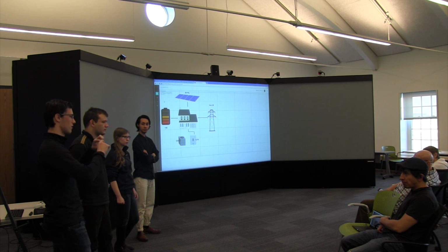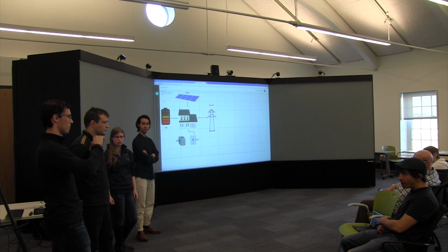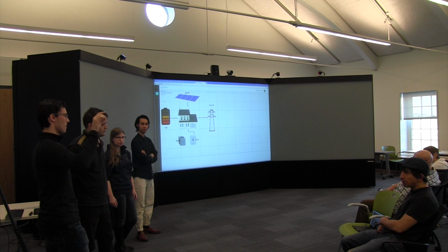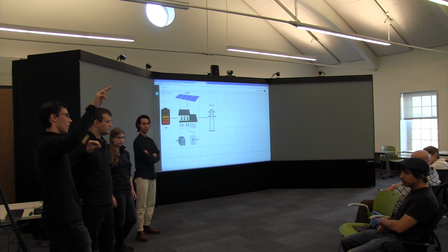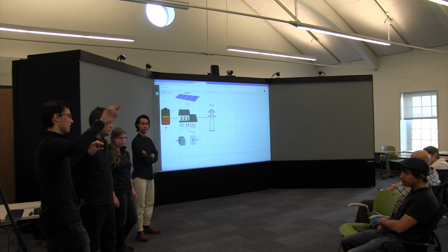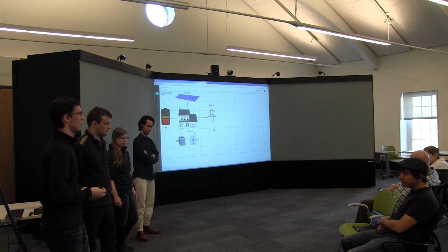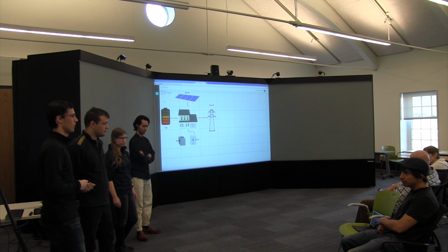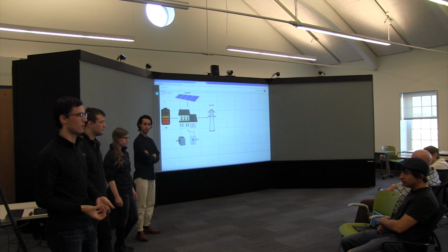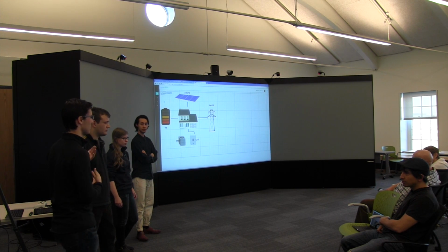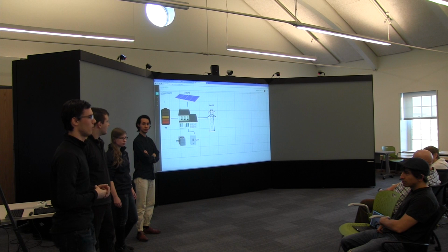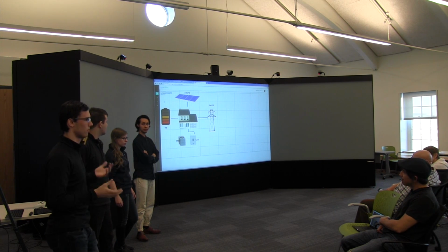As long as you stay within your bounds and are certain you can still meet your frequency response curves, you can buy all the way up to 95% and sell all the way down to 5%. It's not double, but you get about 1.8 times the revenue for implementing something pretty simple, maximizing both sides.